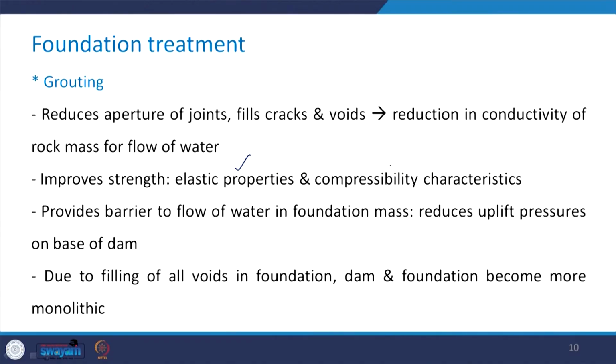Plus, it improves the strength by improving the elastic properties and the compressibility characteristics. It also provides a barrier to flow of water in the foundation mass, thereby reducing the uplift pressures on the base of the dam. Now, due to filling of all the voids in the foundation, the dam and the foundation become more monolithic. So, these are the advantages of grouting.